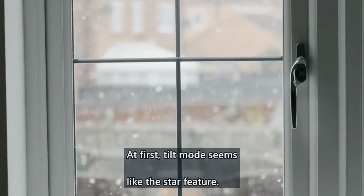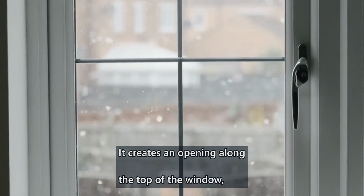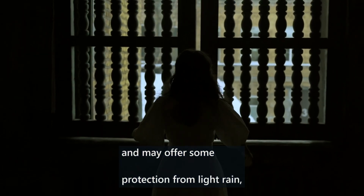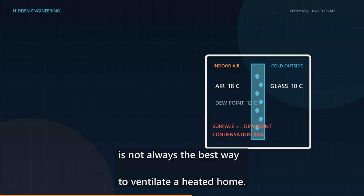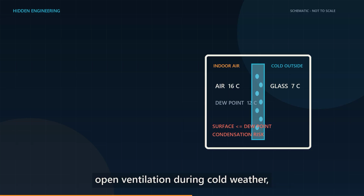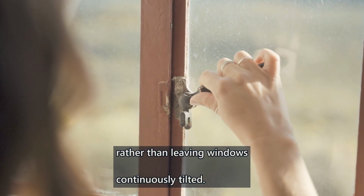At first, tilt mode seems like the star feature. It creates an opening along the top of the window, can reduce the chance of the sash slamming in a draft, and may offer some protection from light rain, depending on the design and weather. But here is the counterintuitive part. Leaving a window tilted all day is not always the best way to ventilate a heated home. The German Environment Agency recommends short periods of wide-open ventilation during cold weather, rather than leaving windows continuously tilted.